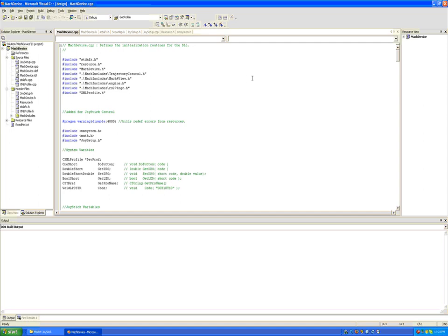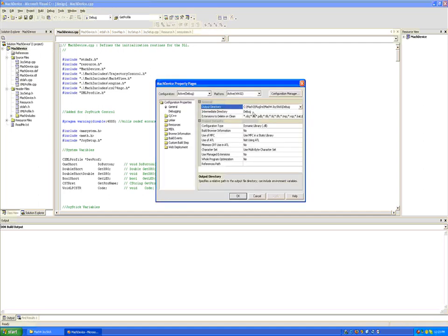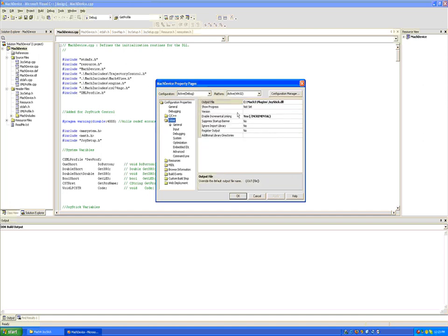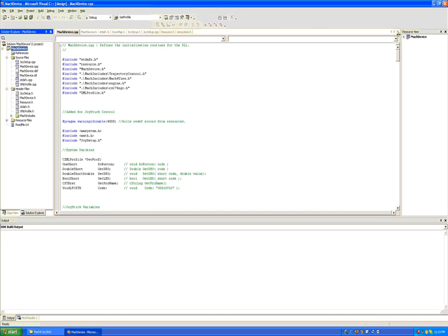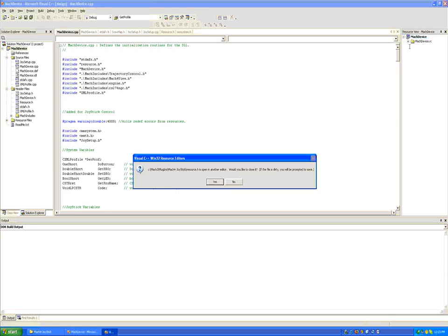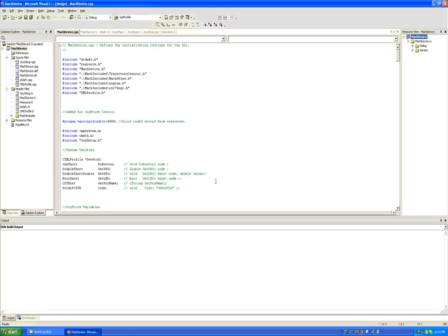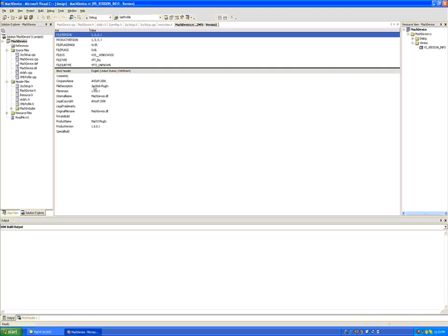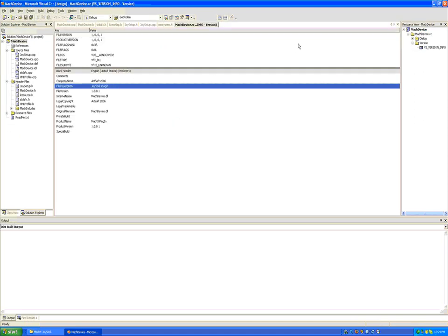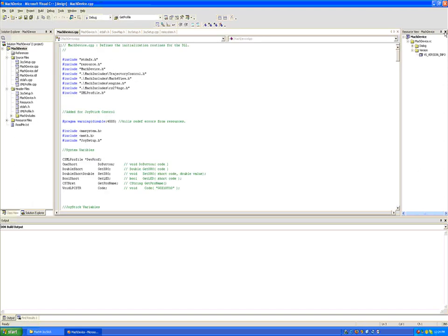One other thing I'll mention is because we're in a joystick SDK, you'll see that I have renamed a couple things to say, under linker, I'm now calling it C Mach 3 plugins joystick.dll instead of Mach device. And under our resources, we now have more than one resource. We have a dialog as well as a version, and inside our version you'll see I have renamed it to Joystick Plugin. Those are the only two changes I did from the skeleton device when I designed this joystick plugin.